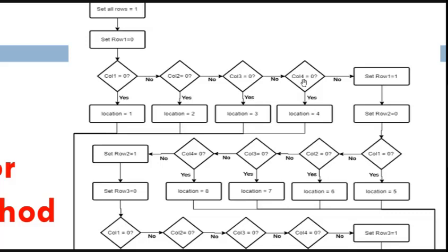And then if you have another column connected, you go for the 5th, 6th, and so on, depending on the total number of columns connected to that particular row. For the example, only 4. So you go checking from the first column, to the second, third, fourth, provided that the output is 0.